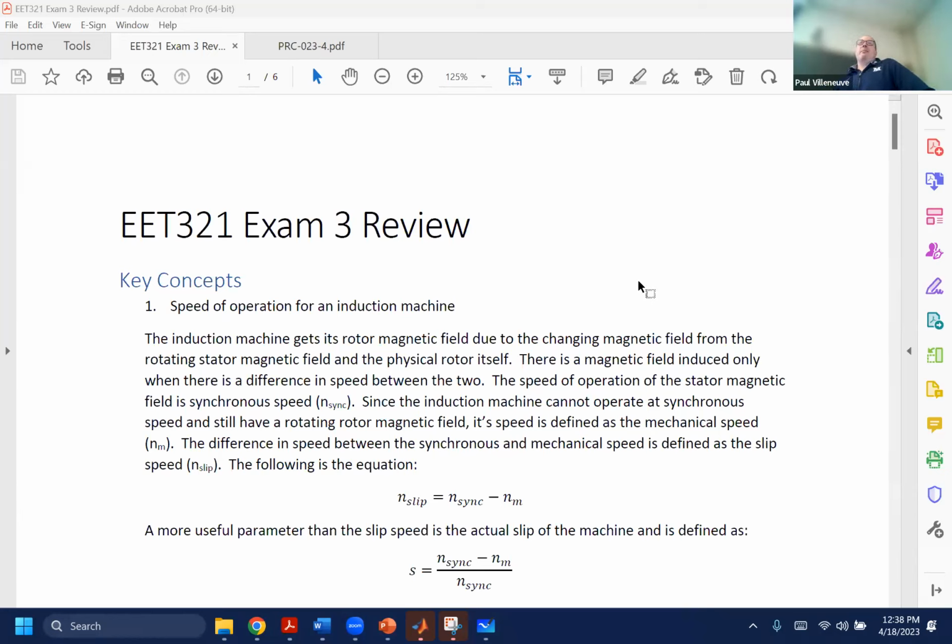They didn't make a big press announcement. They just said 2,000 customers. You can go to Europe and most of their stuff is underground. They don't have those same problems with accidents, but actually overhead lines are supposed to be more reliable for time, because that was a 6-hour outage, but they could replace it in 6 hours. If that was underground and somehow something broke, it would take days for them to dig it up and get all the equipment and the repair stuff. Plus underground equipment is much more expensive and it's not easily stocked on a shelf. So underground stuff usually has a longer time out of service.